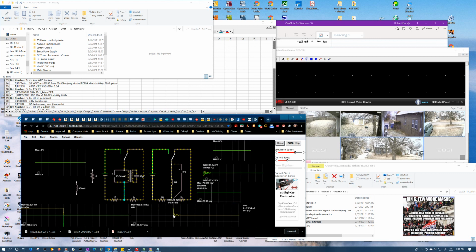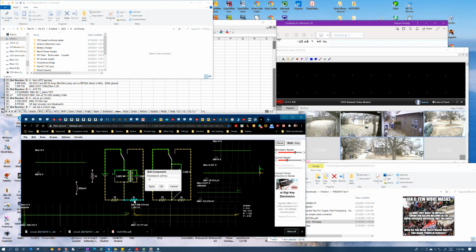And you can see the current waveform over here too oscillated a bit when it hit the ground. So that's basically what goes on with that. Now let's go ahead and charge this up again. Now I'm going to lower the impedances down to 100 that we're dumping these inductors through.